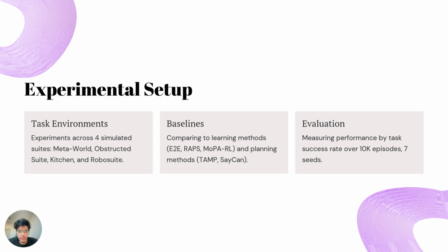What makes PSL stand out is instead of training multiple policies for different task stages, it uses a single RL policy that works across all stages. This policy operates locally, focusing on the area right around the robot, which removes the need for a global view of the entire scene. Stage transitions like grasping or placing are identified through visual pose estimates, and training is guided by environment-specific reward functions.